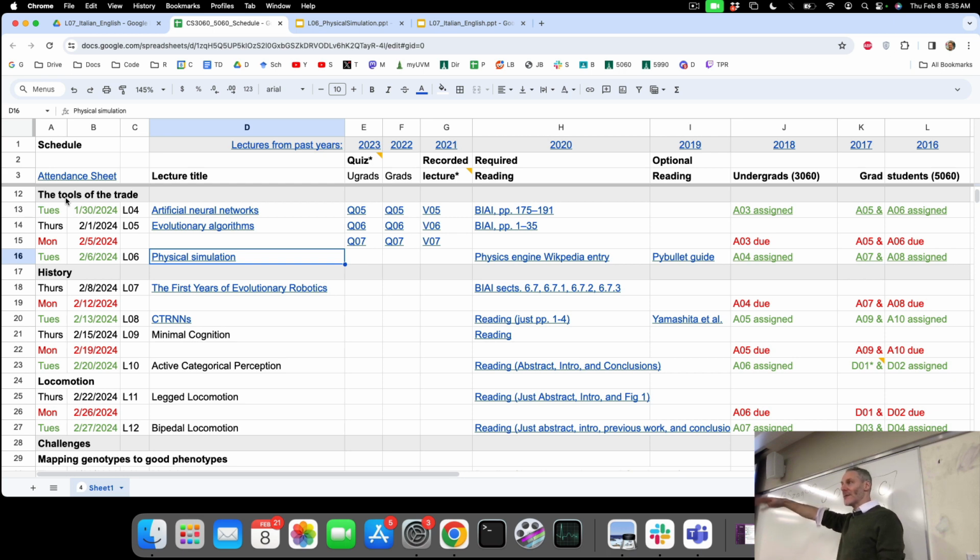We take those 8 synapses, we run it on the Braitenberg vehicle, we see how well the Braitenberg vehicle does at whatever it is we want it to do, and that number that comes back from the fitness function, how well the robot did with that set of 8 synaptic weights, is the 9th dimension. It's the height of that point. So in a 2-sensor, 4-motor Braitenberg vehicle, we would have a fitness landscape that exists in 9 dimensions.